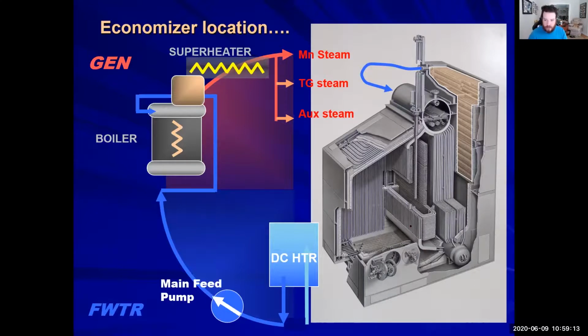All right. So all of those gases, everything that you've used that goes through your generating tubes, through your superheater, back through your generating tubes, it has used a huge amount of energy and it barely can give any more. Well, we're going to give it through the economizer and we're going to try and take as much as we physically can out of it. All right. That's the whole point. That heat is still there for us to grab.